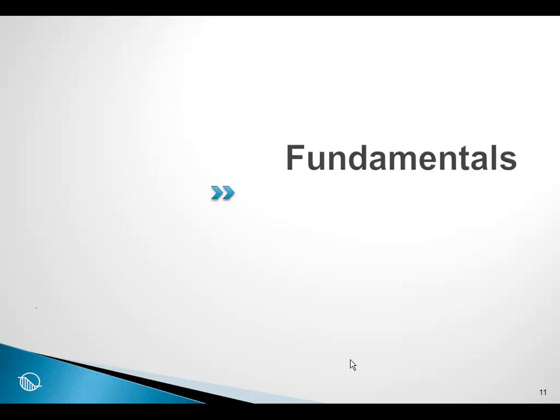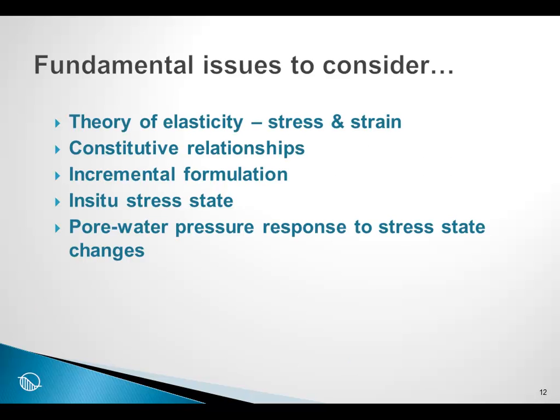Moving on then to some of the sigma W fundamentals. To begin with, there is the theory of elasticity, that is stress and strain. Sigma W is based on the fundamentals of the theory of elasticity. There are several different types of constitutive relationships. Sigma W is formulated on the basis of an incremental formulation, which is very important to understand to use sigma W effectively.